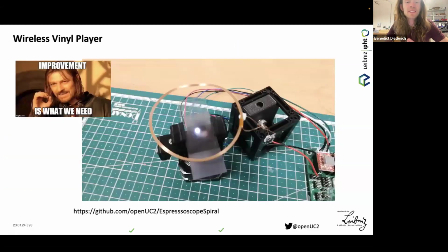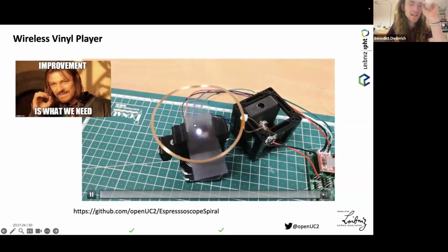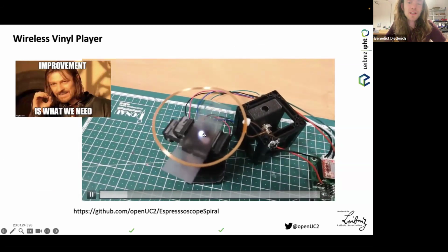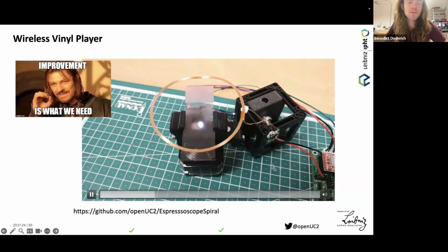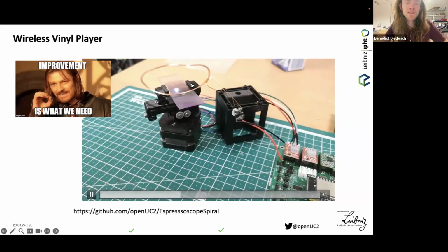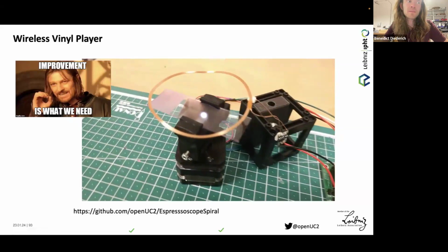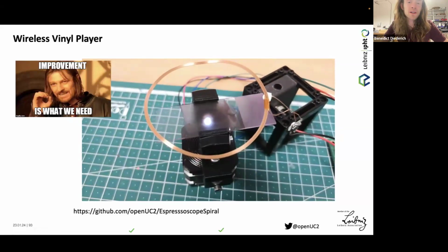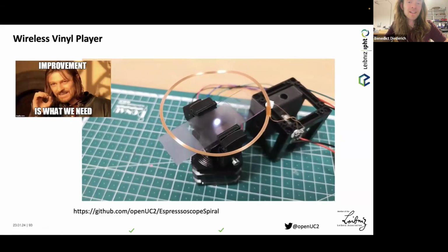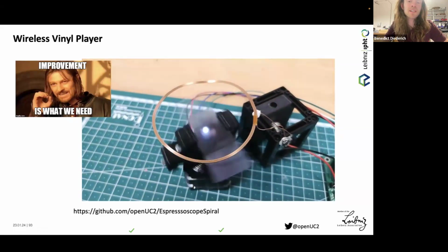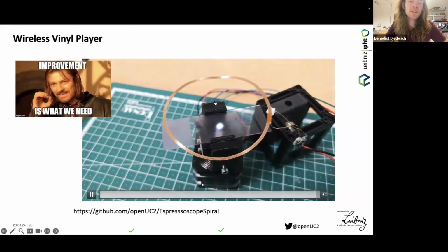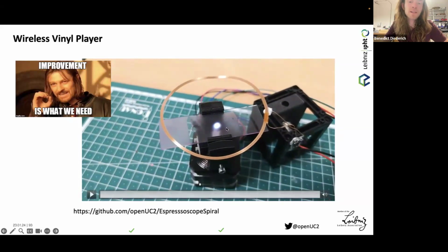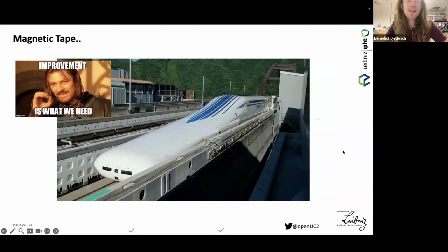That's all nice, but mechanically, that's always a challenge. Maybe this is the next iteration, where we also had a light source that's driven with, again, maker-based equipment. This is RFID-based technology, let's say, where you use induction for getting energy through the air. Not very efficient, but it works. Here you would see the lens coming from above, and then we do the imaging of this malaria blood smear. That's all very nice, but I think we still need to improve a little bit, because mechanical scanning was challenging, because the slide always had a little tilt, so we could not really go for that.